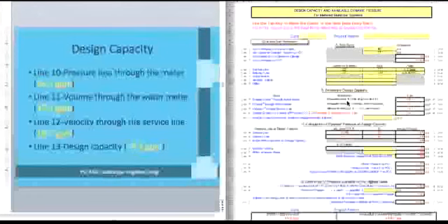The allowable loss through that meter cannot exceed 10% of the PSI up here. So it's saying that the allowable loss cannot exceed 10% of 80 PSI, which is 8 PSI. And that seems like a problem here because we've got 36.4 GPM.